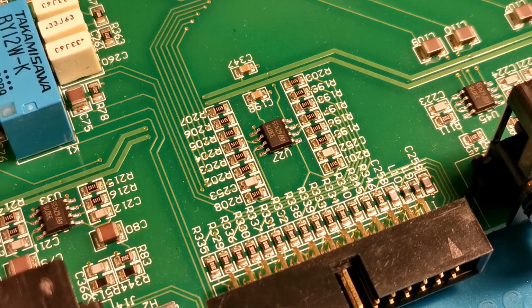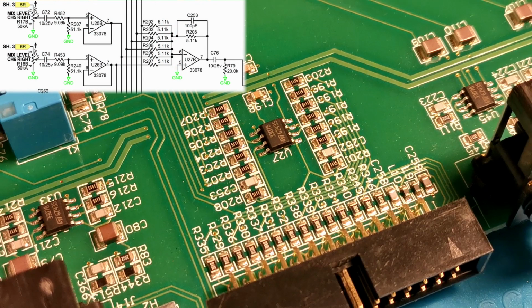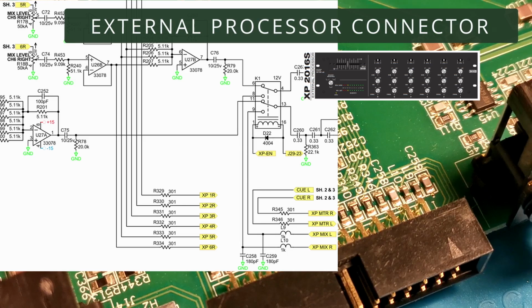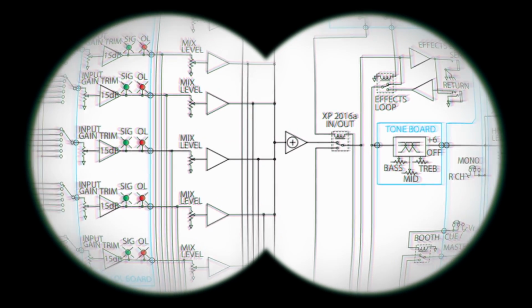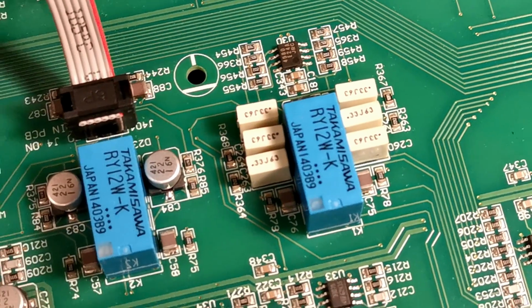Then signal from every channel is sent to the most essential part of the mixer, summing amp. It's also based on 33078 op-amp and uses virtual ground configuration. There's also an alternative path for signals from channel volume circuits. They are also hooked to the connector that allows to send them to external processor. So as I said, there are 2 paths for signals going from individual channels. They are summed directly in the mixer or sent to processor and summed in the processor. The switch allows us to choose from which summing amp we want the signal to be further processed.